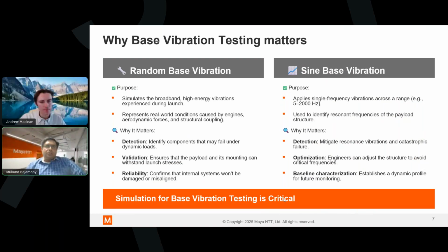Vibration analysis and simulation assist testing by predicting in advance how the model will behave, identifying resonant frequencies, stress concentrations, and potential failure points a priori, and optimizing designs virtually, reducing costly redesigns. They also ensure that physical tests are targeted and efficient, avoiding over-testing or missing critical modes, improving the confidence in the model for future missions and configurations, reducing the need for repeated physical testing,